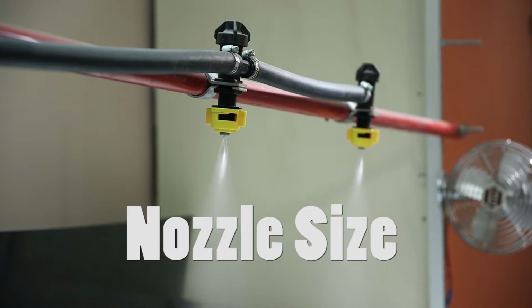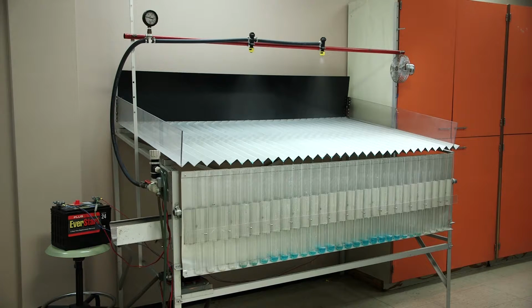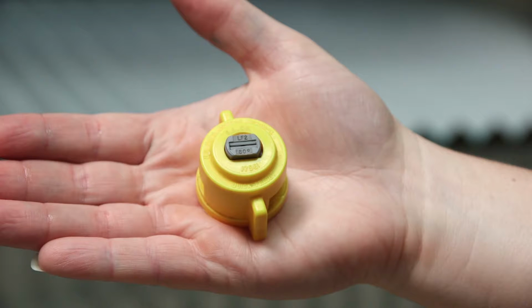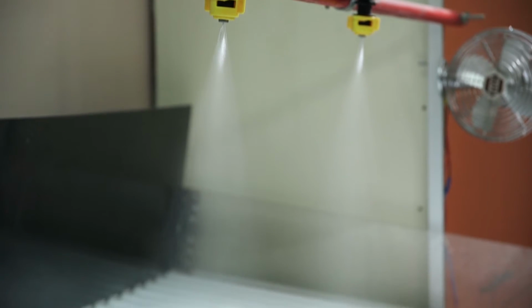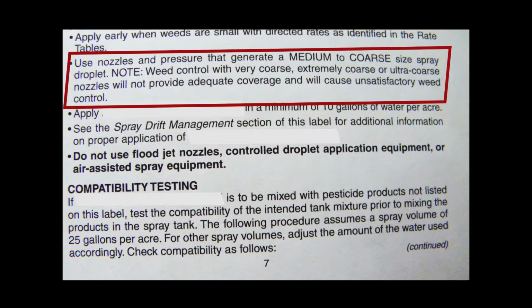The first demonstration compares the difference in applications with two different nozzle sizes. Both nozzles have the same spray pattern, but one has a larger orifice than the other. Now that the nozzles are attached, the pump will be turned on to begin the test. As demonstrated by the water collected in these tubes, the output volume varies based on nozzle size. The larger nozzle has a higher output than a nozzle with a smaller orifice. Choose nozzle size based on application rates and label guidelines.